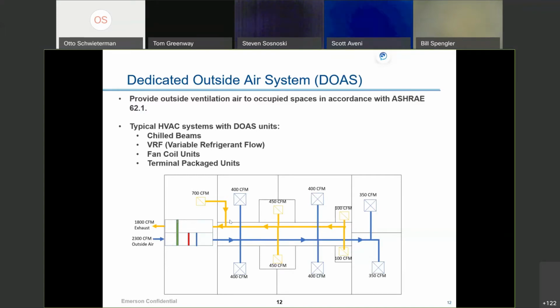So you may have 75-degree exhaust air on this side of the system running through the energy recovery wheel, and you may have 90-degree outside air coming through this side of the wheel. That wheel is going to be slowly turning, heating up and cooling that membrane on there. You're going to have flow across there. There will be a little bit of cross flow, but it's going to be very little, a 1% type percentage of that. So you may have 75-degree return air coming through here and 60% humidity,